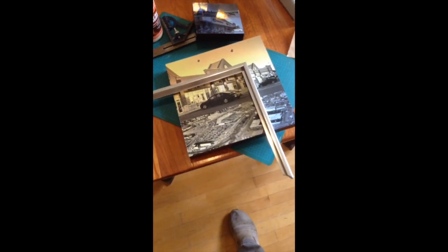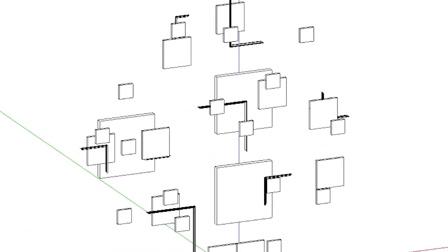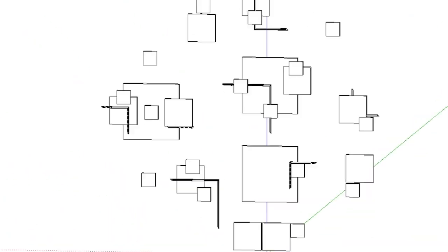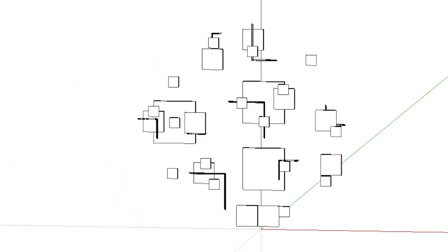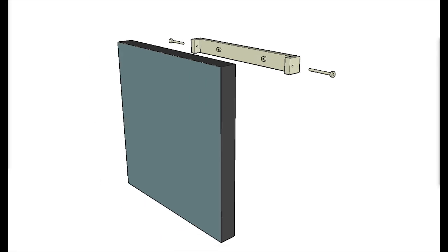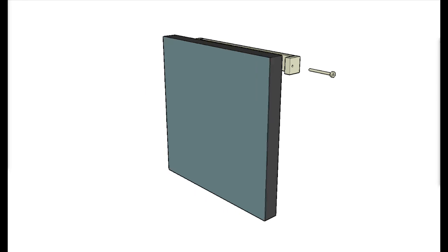So to help keep track of all the various pieces and how they fit together, I made this exploded drawing that showed the individual sections and which ones were attached to which. This was also pretty handy when it came time to do the installation on the wall. To hold the larger panels to the wall, I made this wooden cleat that got attached to the wall with some toggle bolts, and then the panel slipped over the top, and then 2 pins went right through to hold it on the sides. This was probably overkill.